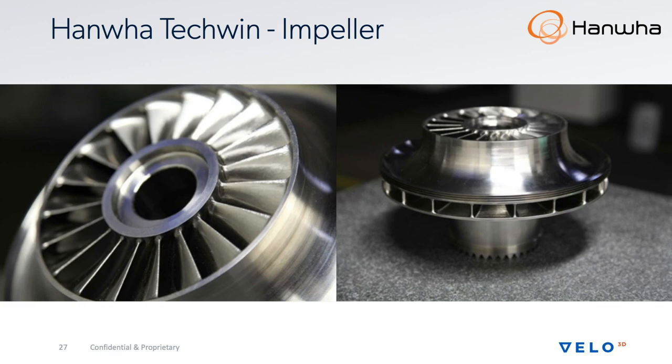And on other systems, again, think about everything below about 45 degrees or 40 degrees is going to have to be full of supports. The removal is very difficult. And then post-processing to get those surfaces back to being acceptable is much, much greater. And so it makes a much more difficult business case for this. So Hanwha settled on using the VELO3D Sapphire system for this, and it came out with a great result. And I encourage any of you to go on our website. You'll see a white paper that was written independently from the contract manufacturer that owns the Sapphire system and a representative from Hanwha. And they do a very thorough analysis of this part. So I encourage you to take a look at that.